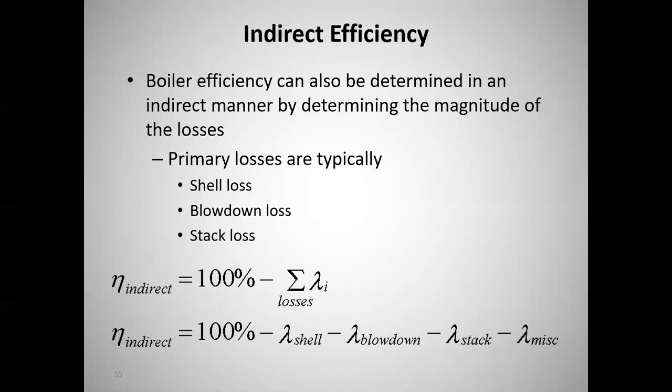Okay, so this is where we wound up last time. So I think I have already discussed this slide, but the indirect method of calculating boiler efficiency, we quantify all of the significant losses, and in terms of a percent of boiler input fuel energy, we subtract from 100. If we included all of the losses and we did it absolutely correctly, we would get the same number as we get from the classic efficiency. But because the classic efficiency has every loss in it, because you're measuring fuel in and steam energy in the steam out, it by definition contains all losses to the system.